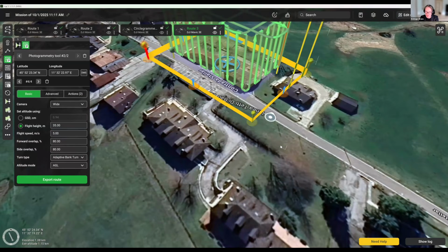So you might have some situations where, let's say, one wall of the building you can easily automate, so you can have the drone scan it. This will give you consistent overlap and good resulting data. But what you can also do is, maybe on some other wall of the building, maybe there's trees or something else that simply prevents you from scanning it. There are also some situations where, in case you're scanning some taller apartment building, you might have some trees around it at the very bottom.